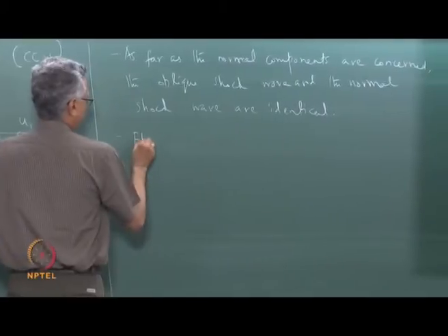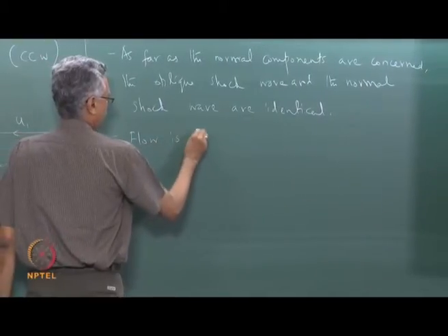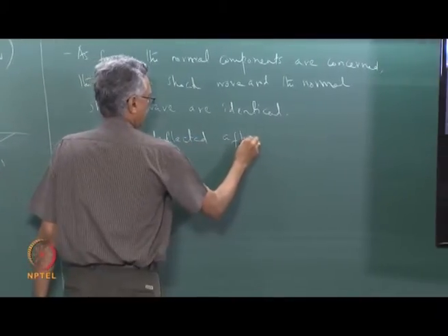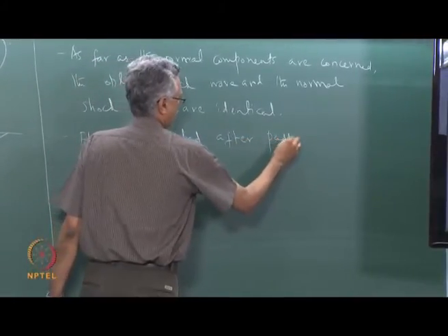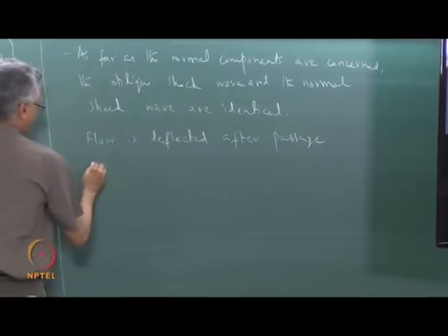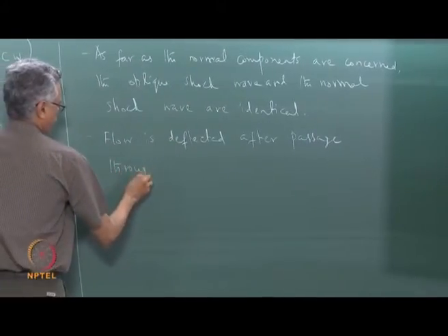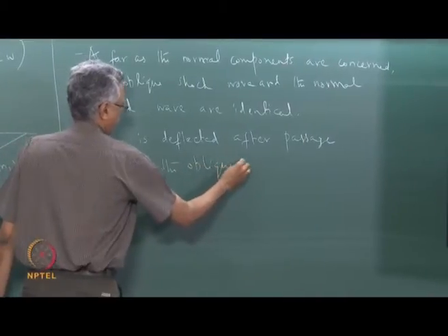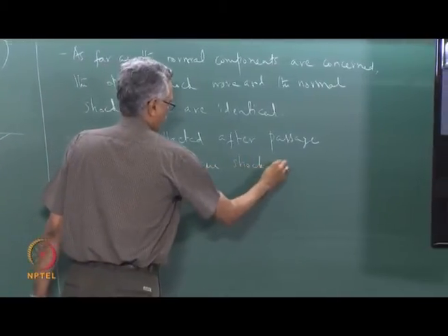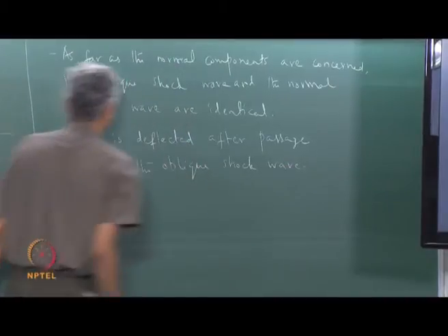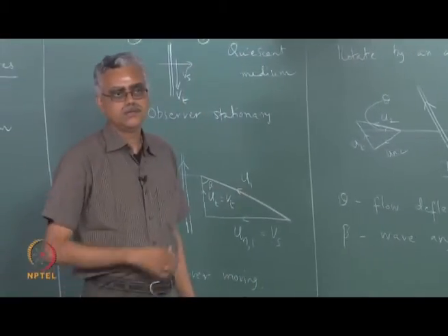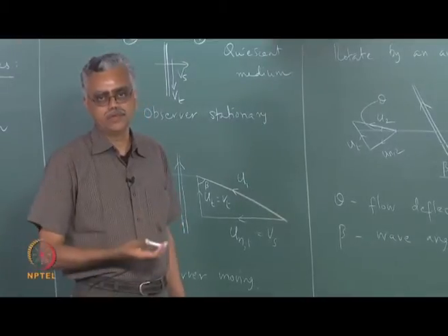flow is deflected after passage through the shock wave. In fact, which way is the flow deflected? The flow is deflected towards the wave, right.